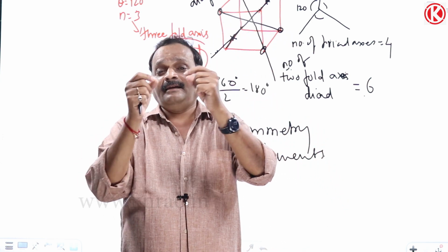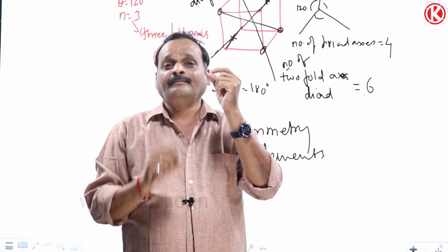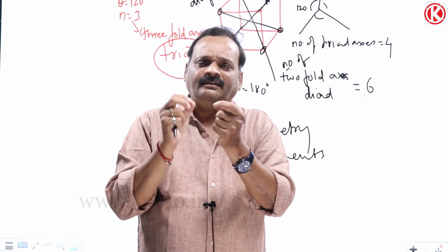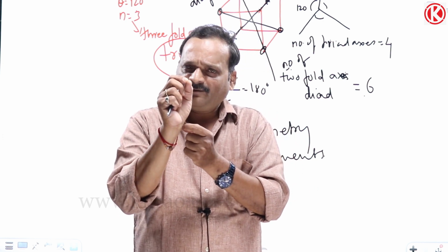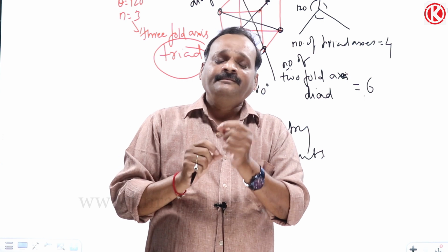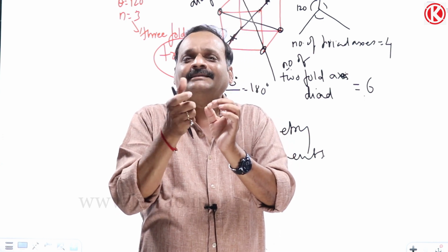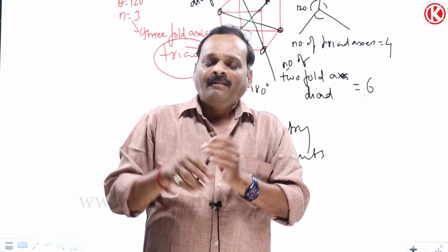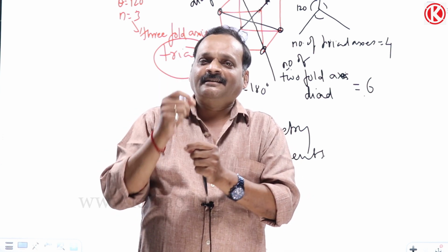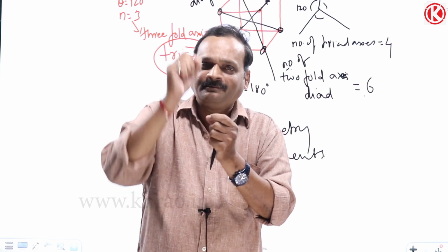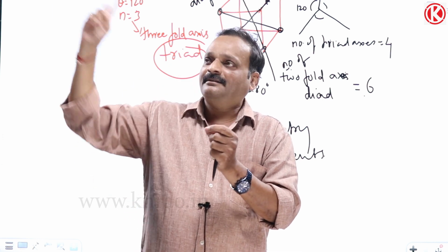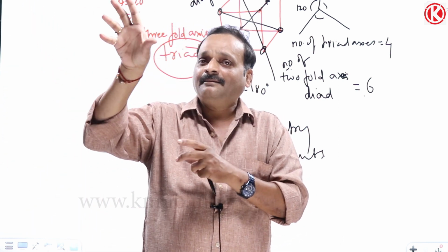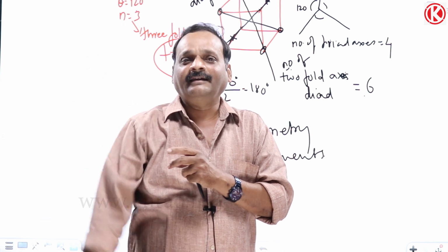Okay, a special case of piezo is pyro. Pyro means even if a very small amount of radiation falls on it, even if you change the temperature by 0.0001 degrees Celsius, there will be a small potential difference. Pyro means heat, fire. That 1 microvolt or 0.1 microvolt potential difference will be immediately amplified by our electronic circuits to 100 volts or 230 volts. One burglar alarm will start ringing.